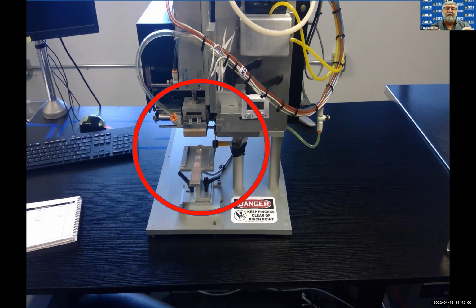Look at the process and put together a system to prevent that person from coming in contact. And again, we can guard in a lot of different ways, and we can spend a lot of time on guarding. You can guard by distance, you can guard by restriction, by fixed guarding, by light curtains, a lot of different things, but leaving it totally unexposed allows that employee to inadvertently get in harm's way.